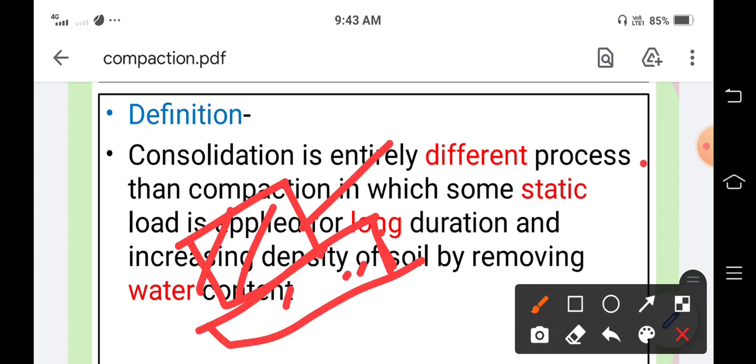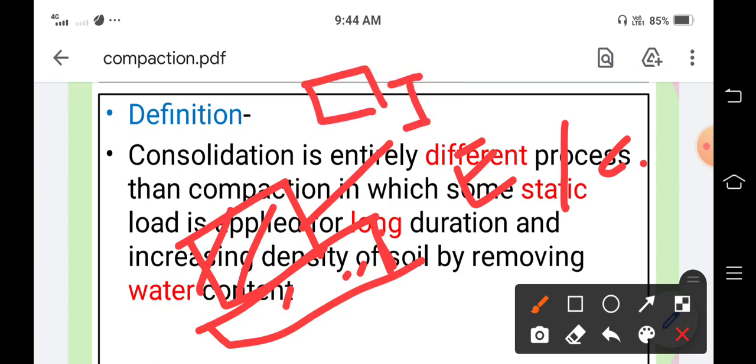First settlement, which is called elastic settlement, and the second one is called the consolidation settlement. So what is meant by settlement? Settlement means this soil strata will start to fall down, or settle in the downward direction, okay.